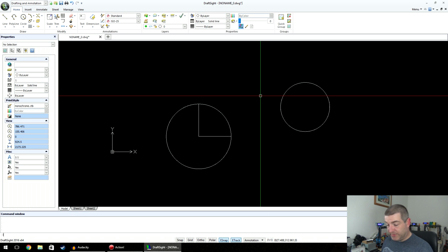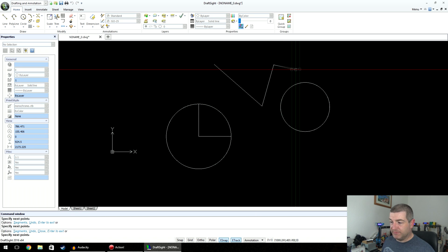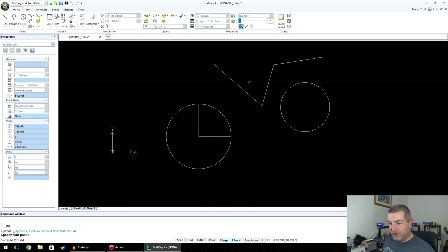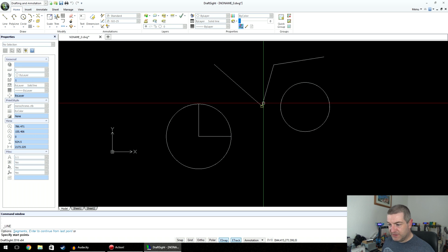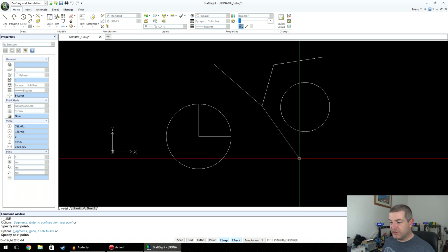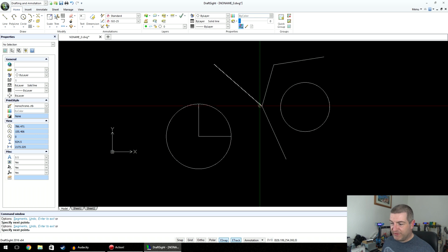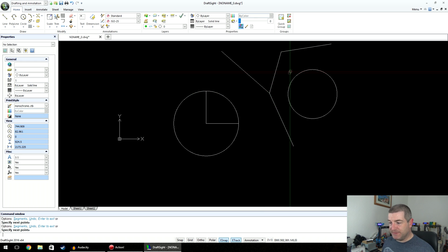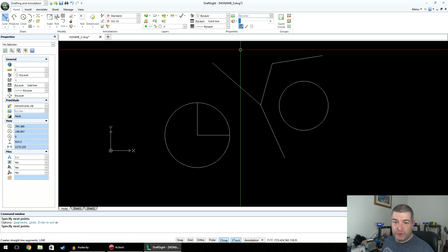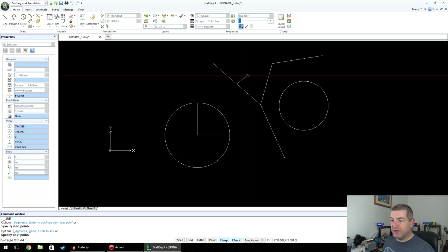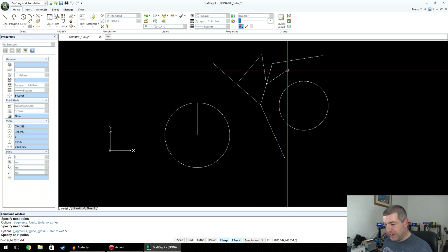So, what about lines? Let's draw a couple of lines in. Now, I want to draw a new line from the end of here. Oh, look, we've got a square one now, and it says endpoint. So I click and drag away. We now have 3 lines that meet exactly in the right place. And we can also do it for the middle of lines. There's a midpoint, it's a triangle. We can click it, and we've got something exactly at the middle of that line.